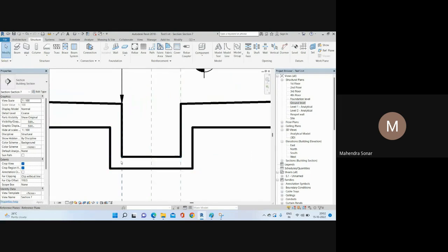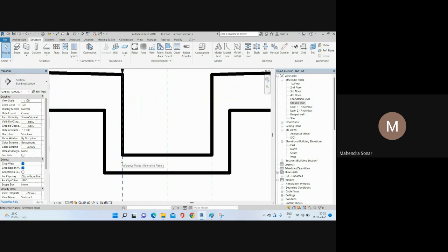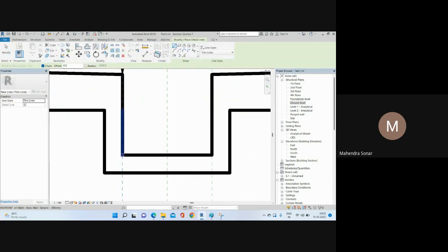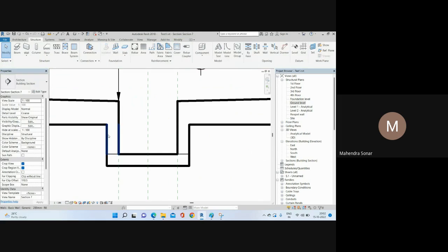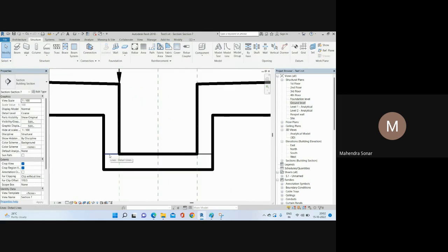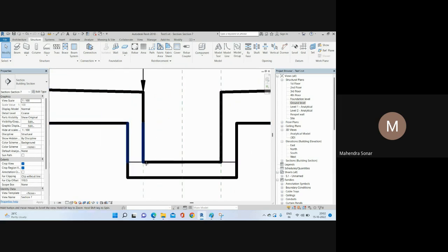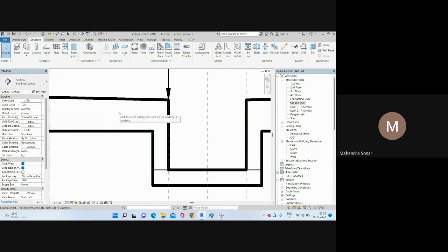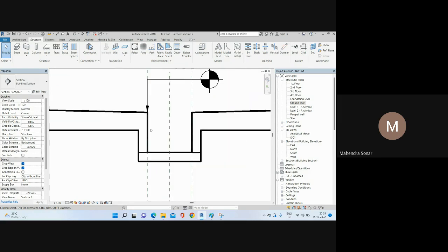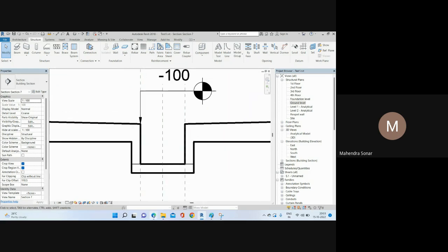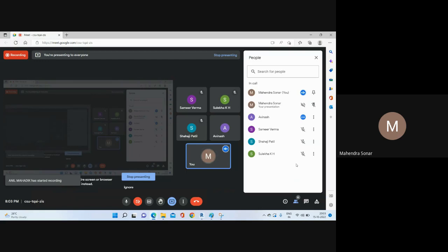Then after that, when we create a 2D drawing, we need to highlight the CJ here. So I will just add a line manually here, and I will show the CJ because my construction joint is here, right? So we are casting this slab first, then providing some dowels here, vertical bars going through this big slab. Okay, we will see this when we jump to 2D drawings, right? I hope everyone is with me.